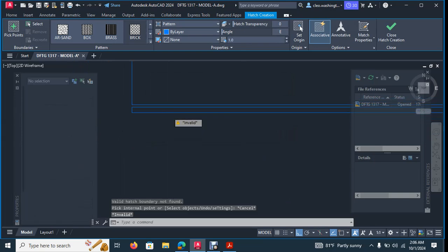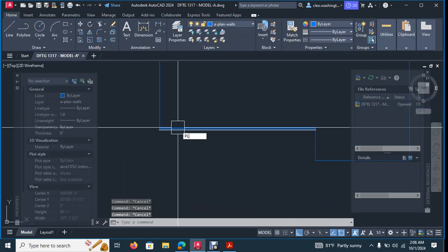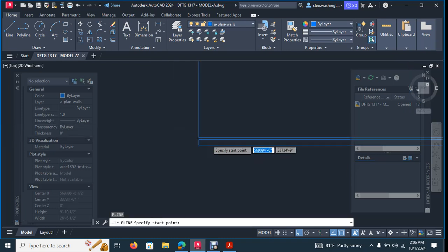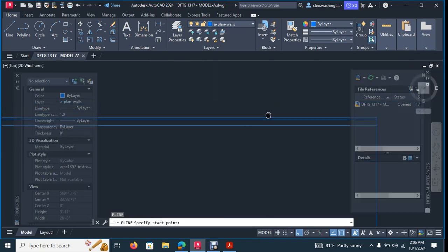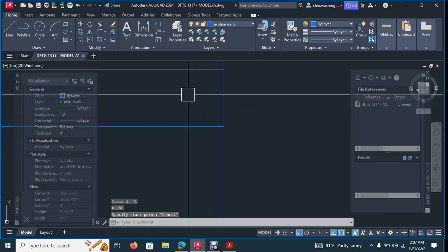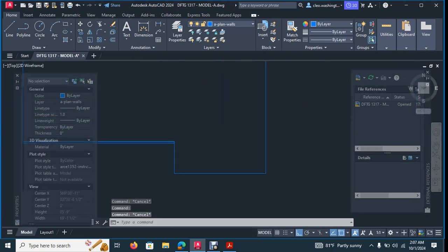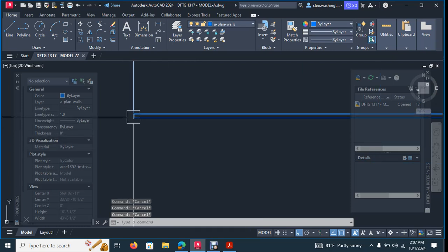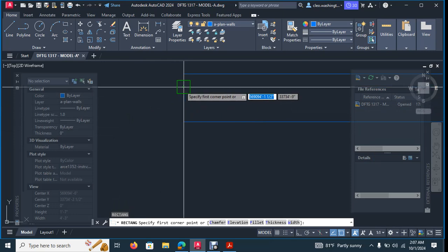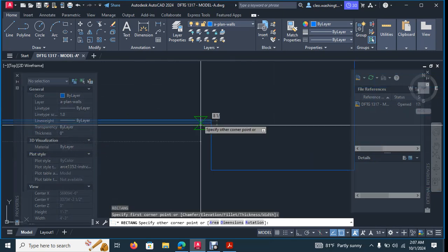Okay, you've got a polyline up. So type in PL for polyline. And sometimes it won't allow you. It's saying that it's not closed. That's kind of why I trimmed it here and put a specific line there. Okay, but let's go ahead and close it. You could actually draw a rectangle to close it, because this one is a rectangle. Just draw a rectangle.